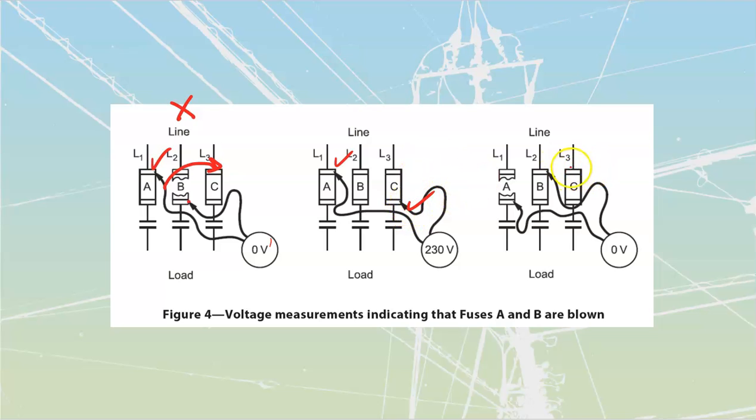because we're getting full line voltage. Move my meter leads, and I'm going to crisscross from the top of either B or C, it doesn't matter, but I'm going to measure to the bottom of A, and I see that once again I've got 0 volts. So I would keep this one on here, and I would then verify that by checking across to here, and it would once again show me that I've got 0 volts.